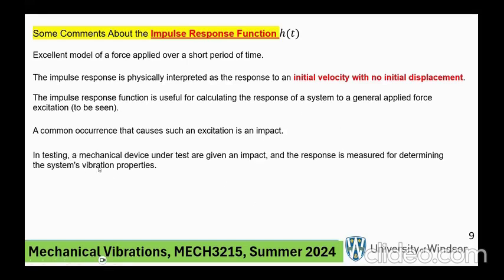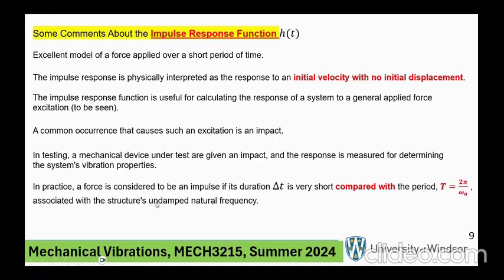Now, in testing devices, people actually use an impulse hammer, and that records for you the duration of time and the magnitude of the force that is imposed on the thing that we are hitting. Of course, it's not going to be constant. It's not going to go to infinity either. However, it'll give you the value of basically the impulse that is applied.